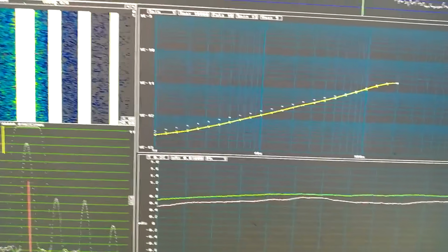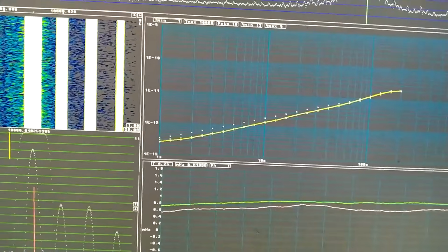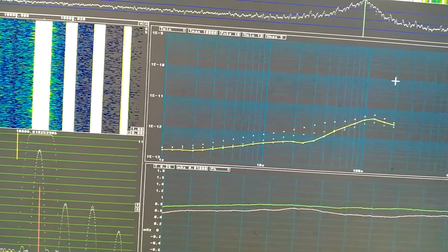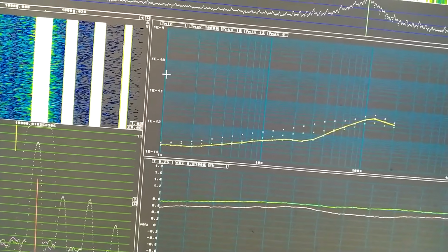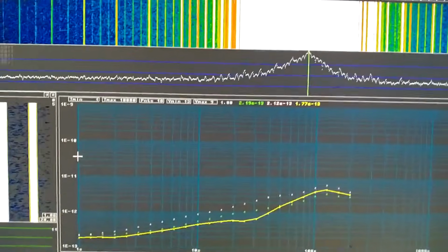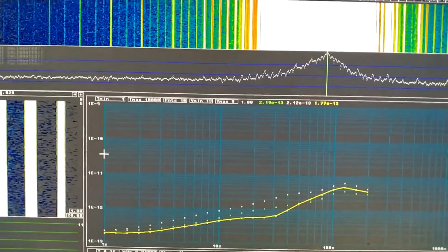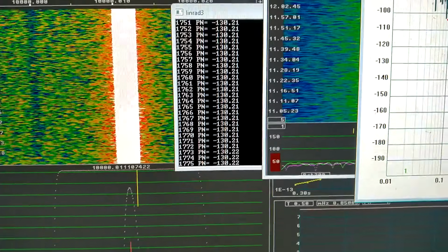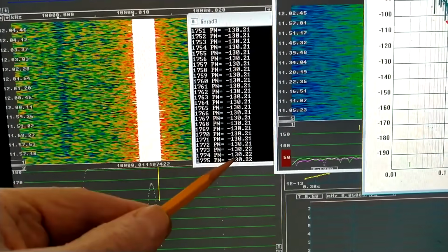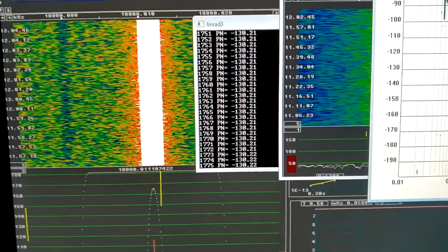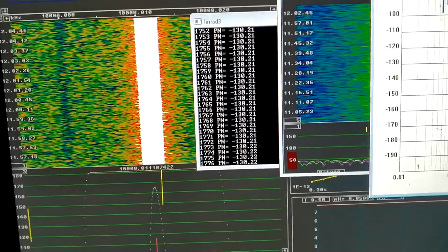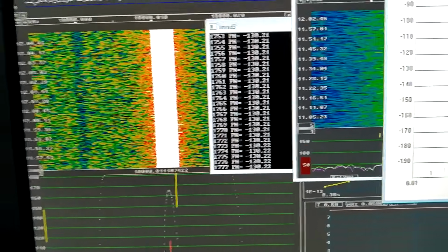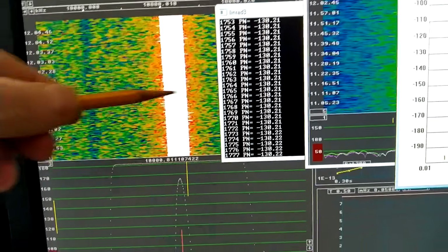Since frequency drift is a major issue here, I can look at the Hadamard deviation. And it's a little bit better at 1 Hz, 1.77 times 10 to minus 13 for the correlated part. The average noise, which I see here, has been unstable. It was hovering around minus 128, but there were occasional events here.